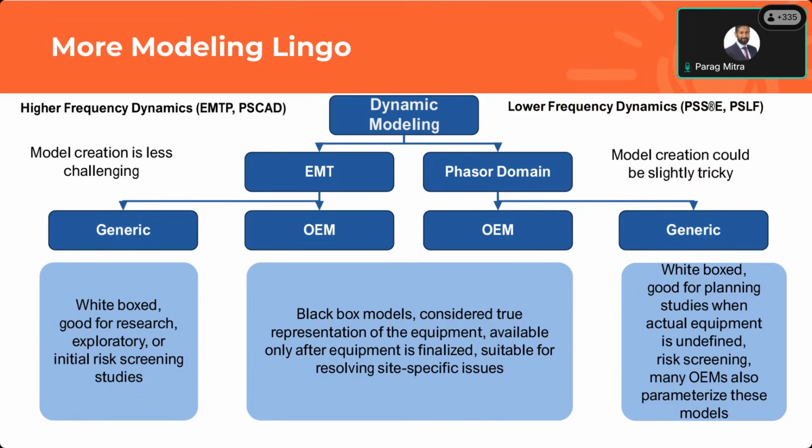Now, that said, with all the modeling, whether it be EMT and phasor domain, one has to always remember that models can always be wrong. It doesn't matter whether it's a positive sequence model or an EMT model. If the model hasn't been developed properly, the model can always be wrong. There are even instances where OEM models have discrepancies and they're not a replication or a good representation of the actual devices. So we have to be very careful when we look at the models.